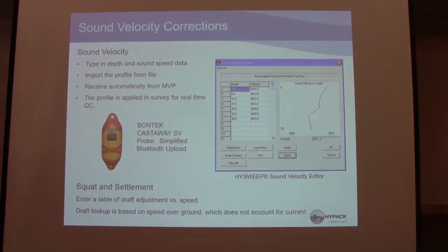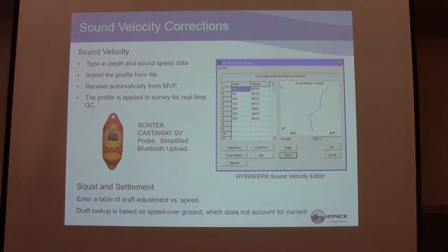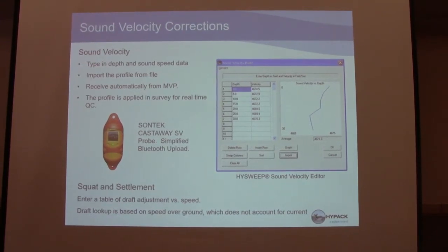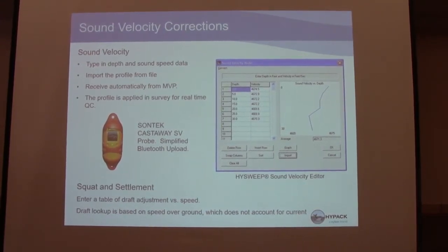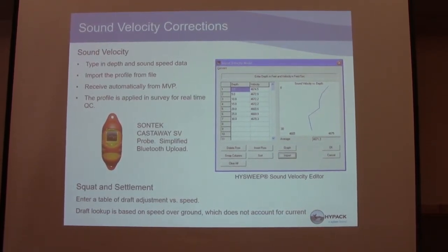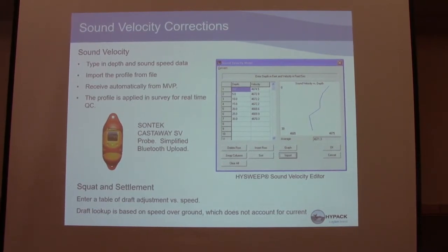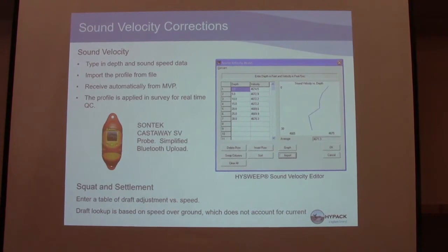They have GPS embedded inside of them, and obviously they have a timestamp, because they've got a position and a timestamp, and it's also collecting the sound velocity at depth. So if we know all of that, we can apply the right sound velocity value at the position where the ping occurred, or close to it.